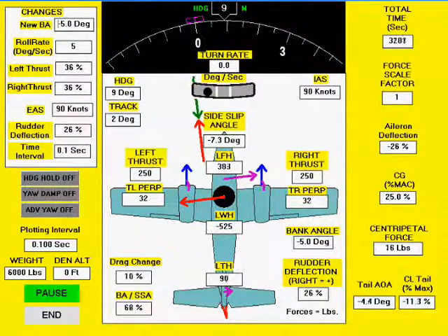We now see that the horizontal component of wing lift cancels all of the forces created by the rudder deflection, making the centripetal force 0 and stopping the turn. We are now looking at a slip. In the slip, we are flying sideways through the air, which allows us to cancel a crosswind while keeping the landing gear aligned with the runway centerline.